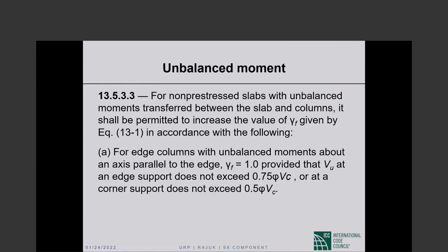I told you under gravity, it is pretty limited unbalanced moment transfer except at the exterior support. Under lateral load, that is not the case. There is significant unbalanced moment transfer at every support.